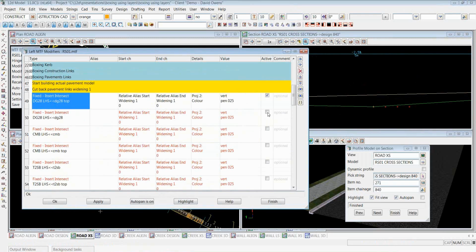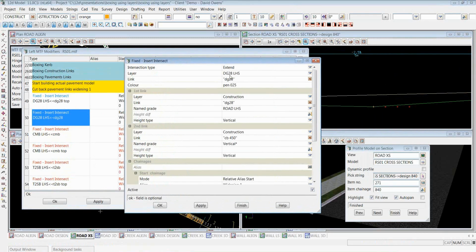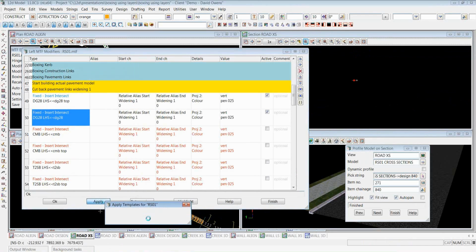And then the point immediately below that. Probably could have done it with an insert absolute command, but easier just to use the intersect because I can just copy and paste and then just change something. And the only thing I had to change was the construction point and the name of the link that's being constructed. Okay. So a big fan of copy and paste, means I don't have to keep typing in new things all the time. Okay. So as we're running this,